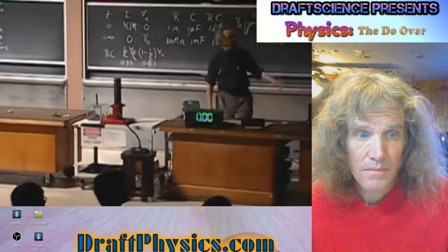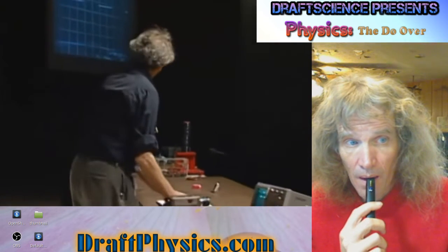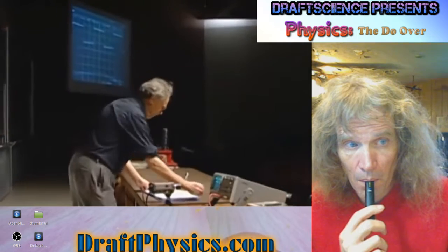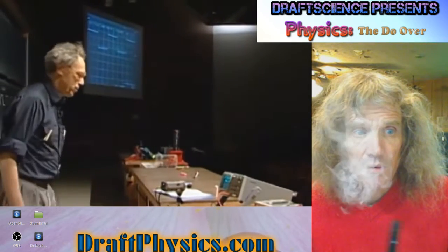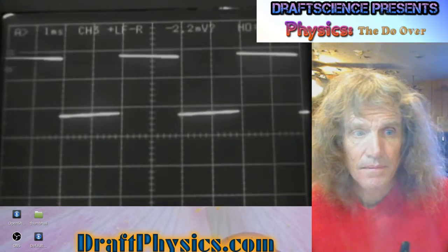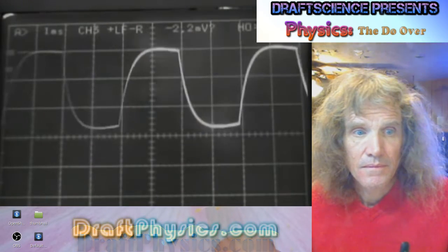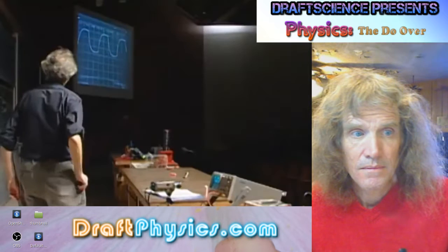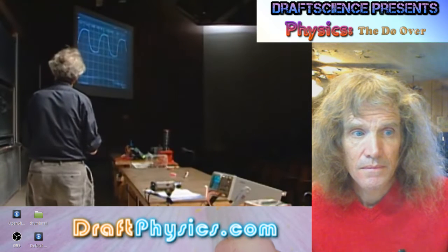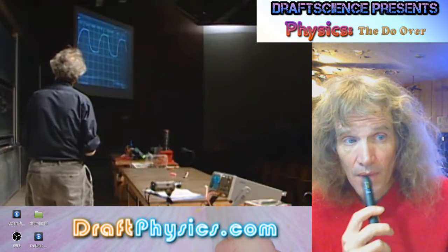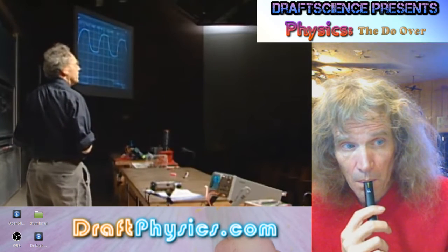You already see there the switching voltage between 1 volt and 0. And now I'm going to show you the voltage over the capacitor, and I will take the other one out. Here you see indeed exactly the image that we discussed. So you see early on the charging of the capacitor, and it reaches effectively the maximum value.